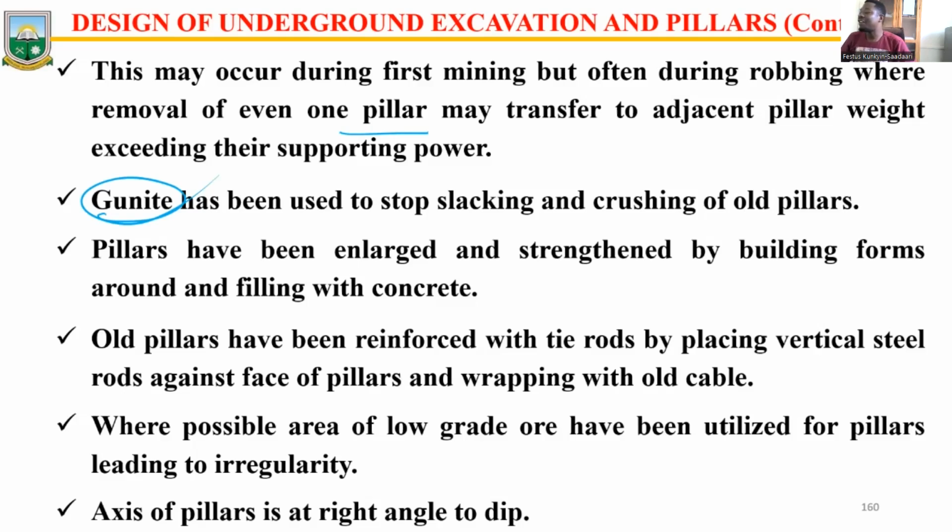Then pillars have been enlarged and straightened by building forms around and filling with concrete. So then we have old pillars that have been reinforced with tie rods by placing vertical steel rods against them. So it's just like where I have a pillar, just like we do with electric poles. Or when you have a plantain and it's about to fall, you prop it up with some kind of steel or wood. So you can undertake some of those activities at old places where you think there's that likelihood of your pillars being weak.